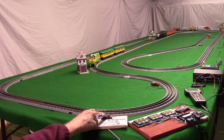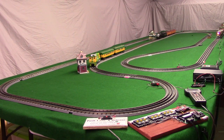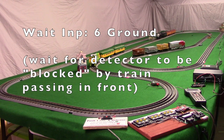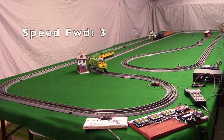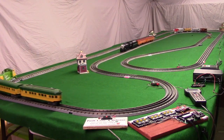All right, we'll push our start button, and we did a select loco 24 and a speed forward 8. Now the next thing that will happen is when that crosses in front of the detector, we'll send a speed forward 3 command to slow it down. It's already selected, so right about now when that goes to red, we say speed forward 3, then we select the green one, 779, we say speed forward 8 to put it out on the main line.